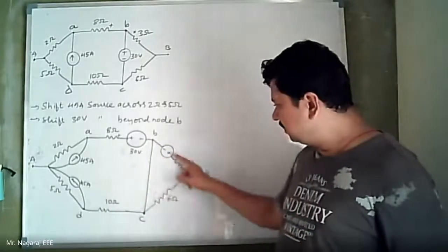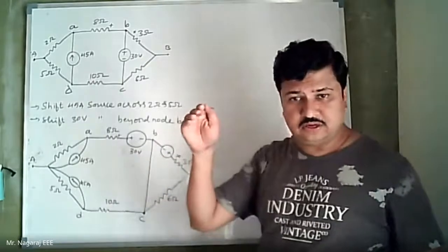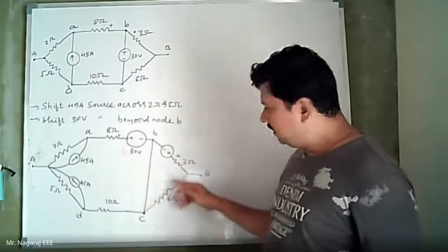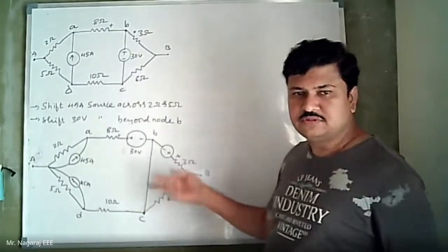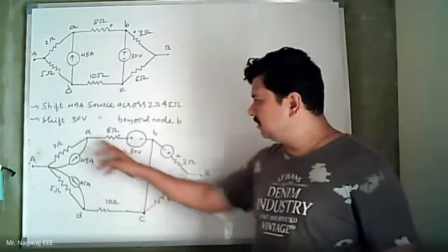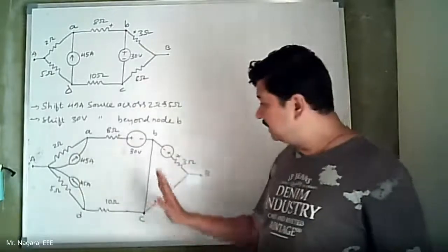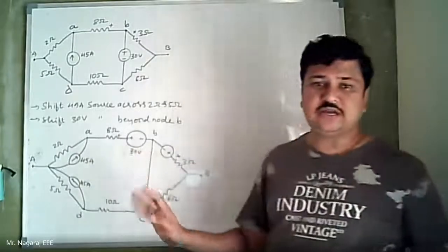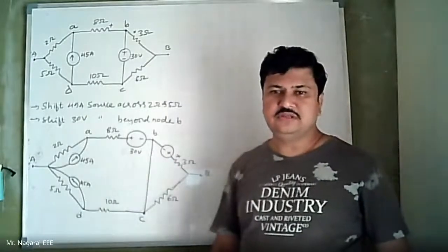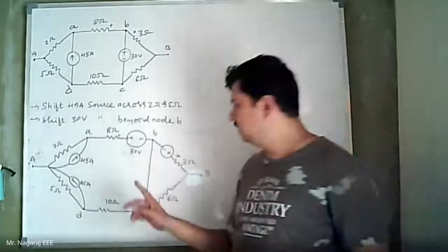The equivalent voltage here is zero, equivalent voltage here is zero. That is actually true as per KVL. If you apply KVL to this loop, sum of all the EMFs and drops is zero. It is true. But it appears that these two parallel circuits are connected across a short circuit which yields zero voltage. This is the general mistake students make when solving this example.